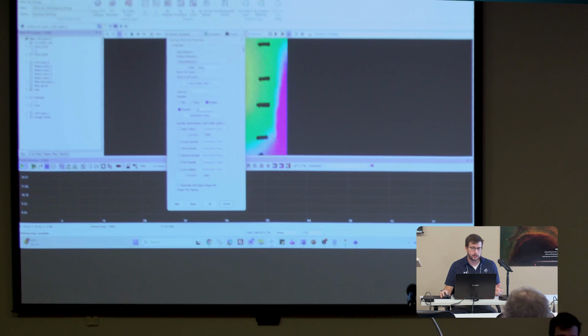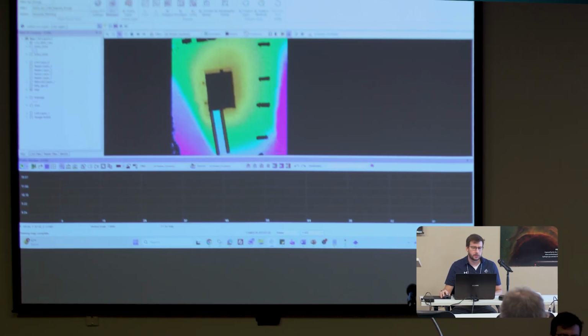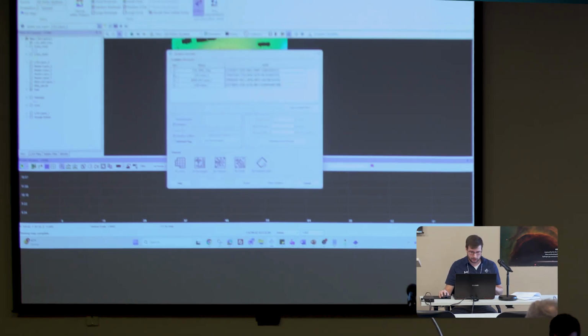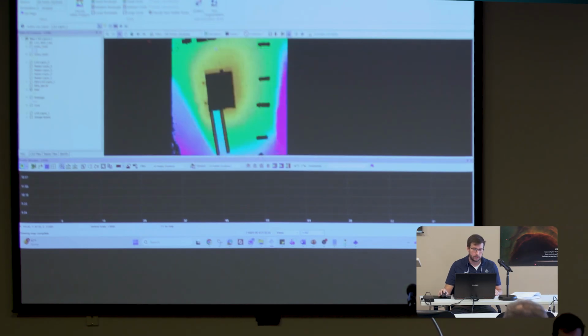And so you can check this. If you go to classification here at the top, this is kind of an Easter egg too. Go to outliers, select our LAS layer. I'll select LAS layer 2 because I know it's already a thin data set. Click estimate point density. You can see what the point density is. You see we're still at 83 points per square meter there. But let's run this on this small little data set real quick.